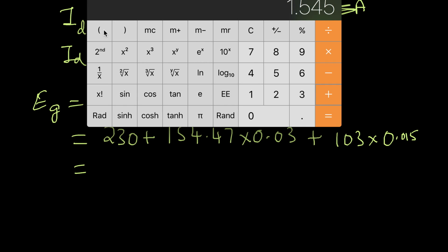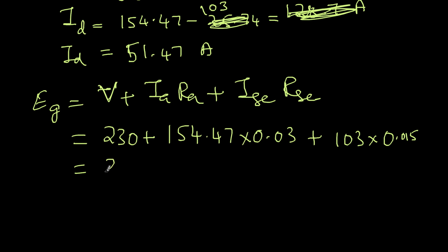So hopefully this is all correct. 236.179, or 236.18 volts. So this is the EMF generated. Brush voltage drop is not given, so I am not considering that.